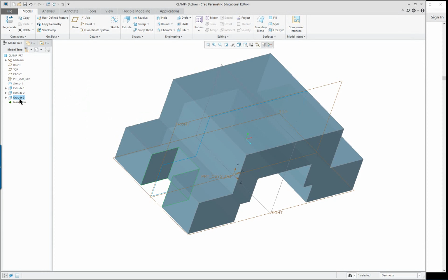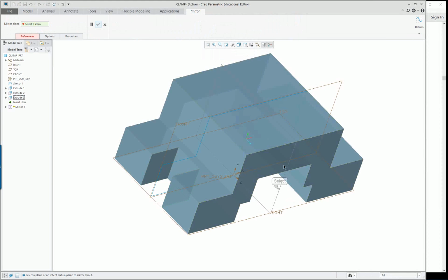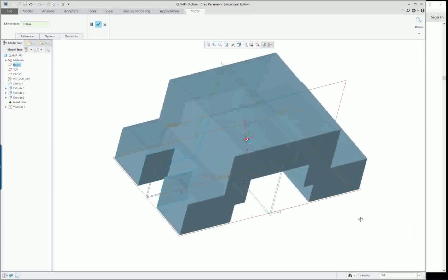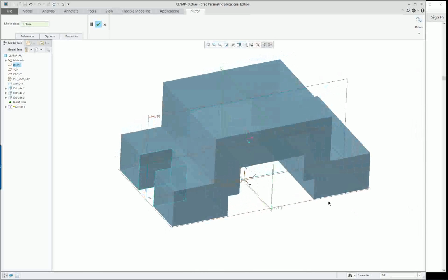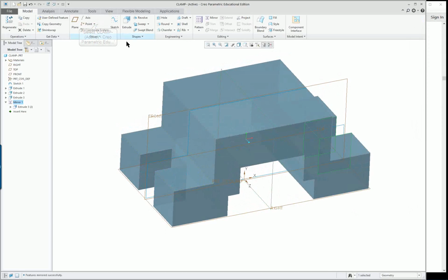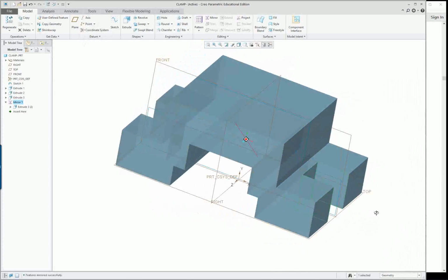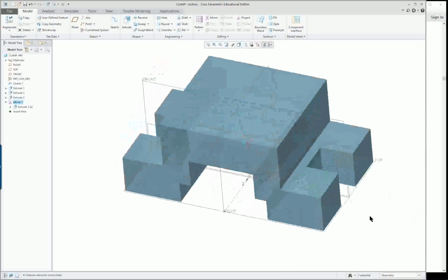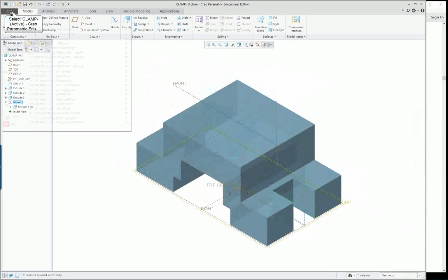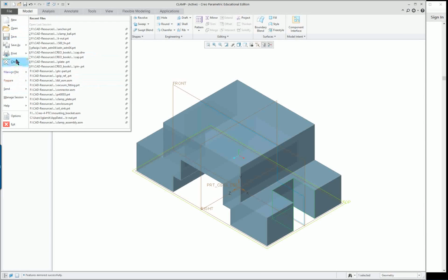So this is still available. If I click over here, it unselects it, deselects it. And if I go up here, I'll see that the mirror tool is not available. But if this is selected, the mirror tool is available. So I click on mirror, and I click on over here, and check. And there's my, didn't preview, and there's my mirrored feature. Control D. Now, if I wanted to, I could save it, obviously. I'm not going to save mine.